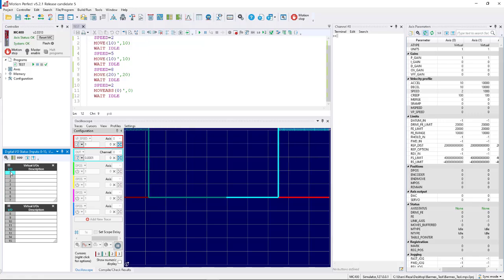So this is a very good tool if you want to display the moment of the activation of the digital input, for example, combined with the position control, so you can plot the moment, and then you can do the troubleshooting if something unusual happens. So the digital inputs and outputs, as you see, can also be on the plot as well.